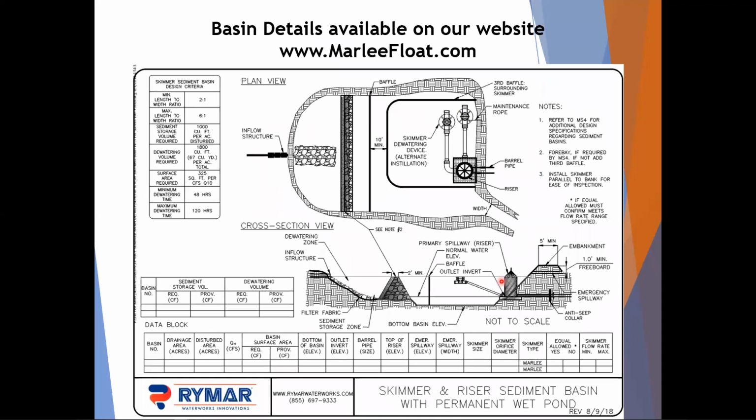And we have a basin detail for that as well. This basin detail adds the sediment storage volume and dewatering volume here. It adds the required sediment storage up here. Everything else is pretty much the same. This version has the permanent outlet structure, a riser setup, whereas the other detail I showed had more of a temporary outlet structure detail.